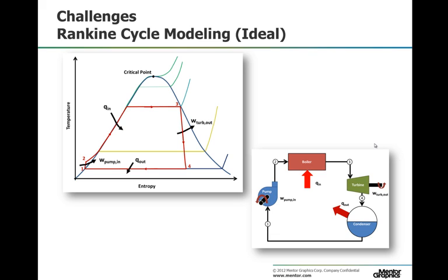Finally, step 4 to step 1. The wet vapor then enters a condenser where it is condensed at a constant pressure and temperature to become a saturated liquid. The pressure and temperature of the condenser is fixed by the temperature of the cooling coils as the fluid is undergoing a phase change. This is the theoretical Rankine cycle, but there are several variations of this that occur in the real world.